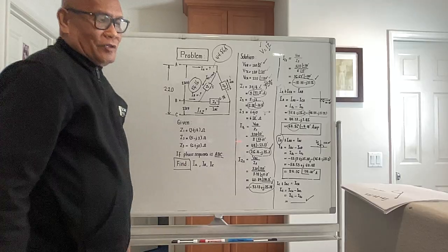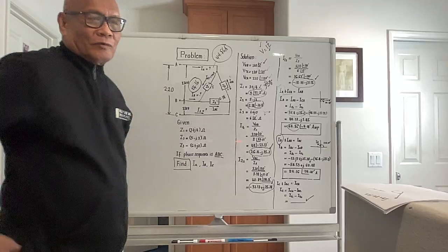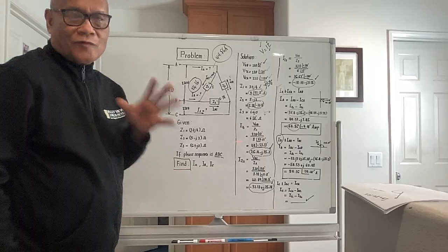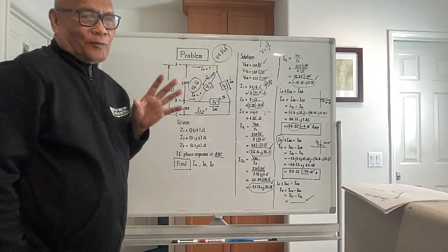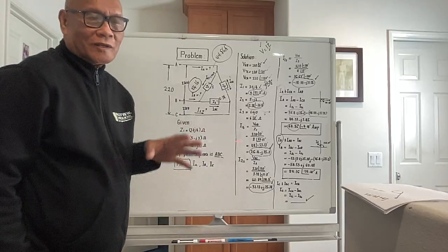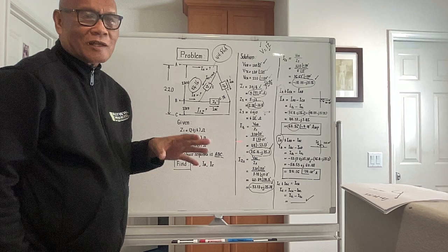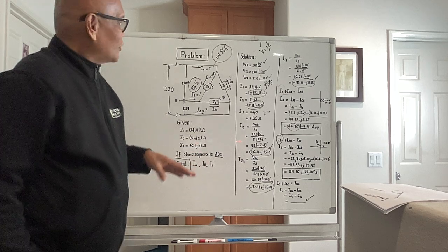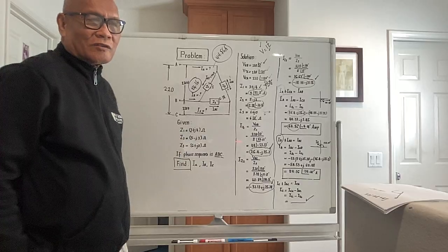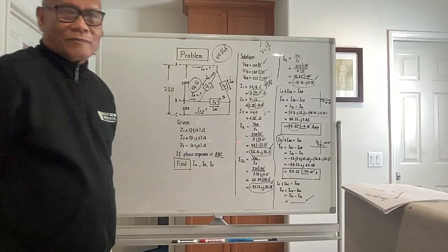This is actually the topic of computation of line currents for an unbalanced three-phase load. The input voltages are balanced, but the loads connected in delta are unbalanced, so the current in each line will be different. That's the worst case scenario in real life.